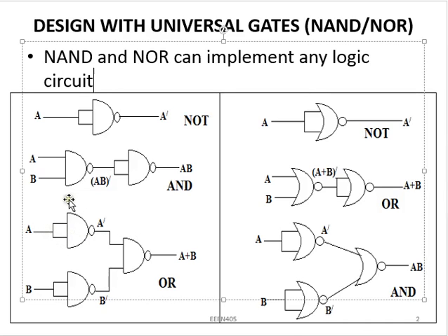If we want to implement OR gates using these NAND gates, all we need to do is to use 3 NAND gates. As you can see here, we pass A to one of the gates to give us A prime, B to the other one to give us B prime, and these A prime and B prime are now delivered to the third NAND gate. Then we will have A prime, B prime, all prime, and if you use De Morgan's theorem, it will be the same thing as A double prime plus B double prime, which is equivalent to A plus B. That is OR implementation.